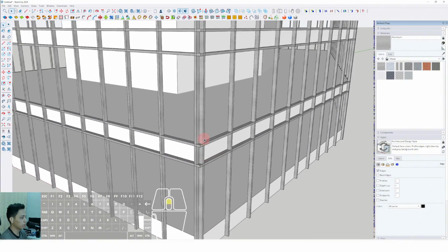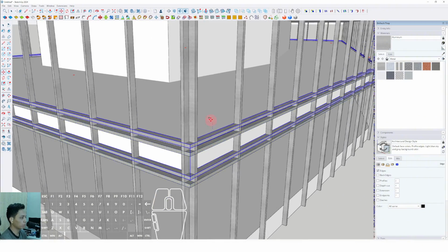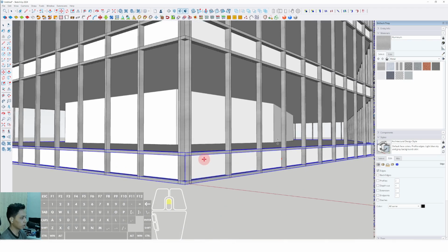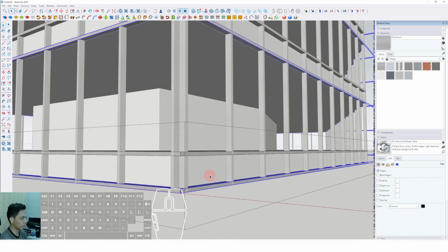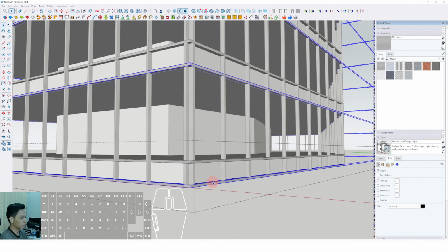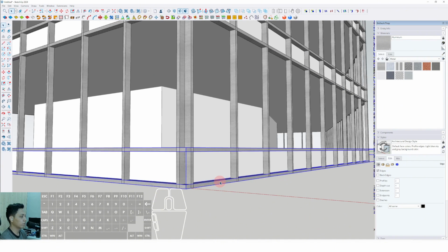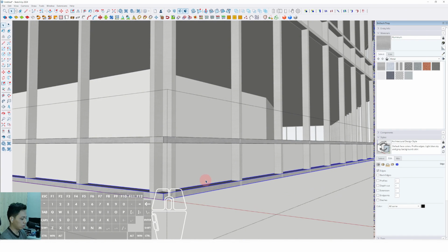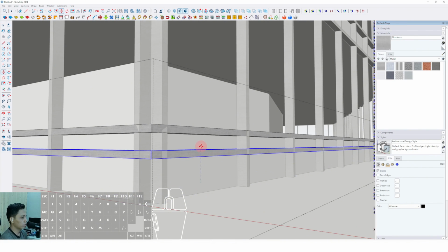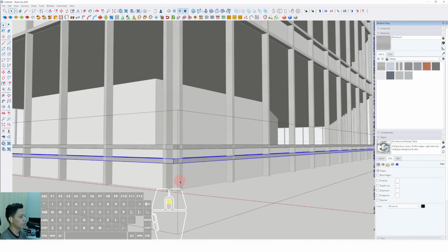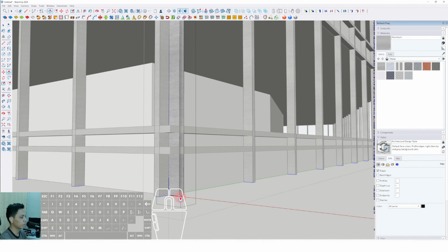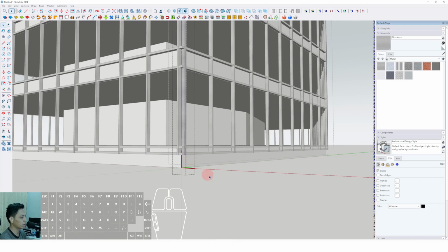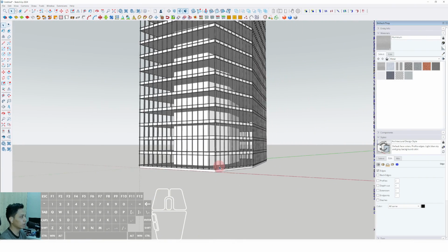Then we have to add one more vertical frame duplication in the lower level of this slab of this typical floor. Then we have to click this one, right click and make unique, select a move of this vertical frame, select move round 600 millimeter and adjust the vertical frame to be the same level on the bottom level of it.